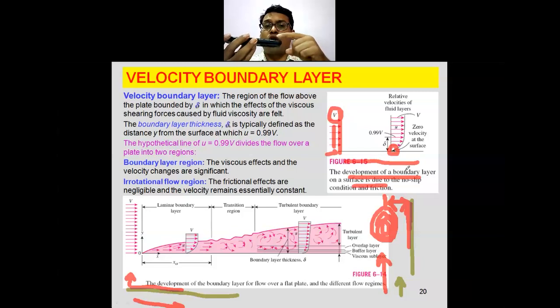So this is the contact with the surface. There you can see the velocity as zero at this point. This is the first understanding. Why is velocity zero? When the liquid particle hits the solid surface, there is no forward movement. It may take a different path and then can get velocity, but at a moment it is going to stay stationary. So the velocity on the surface becomes zero. That is the first point.